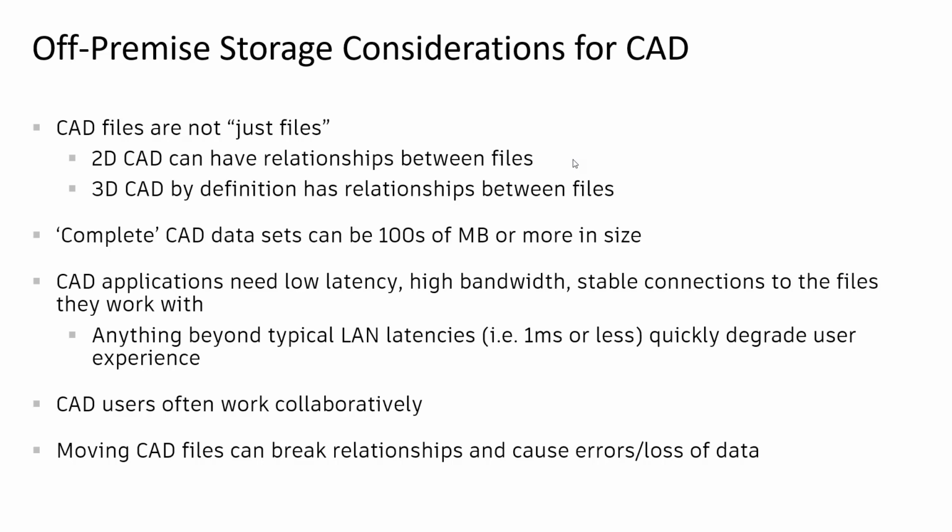What that means is you really need a low latency, high bandwidth, and maybe most importantly, stable connection from your CAD application running on your client to wherever the files are stored on disk. You need extremely low latency. And if you use something like Procmon to see how Inventor, for example, interacts with a file system, it is hundreds and thousands of file operations as you're working.